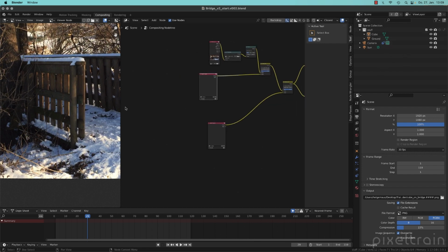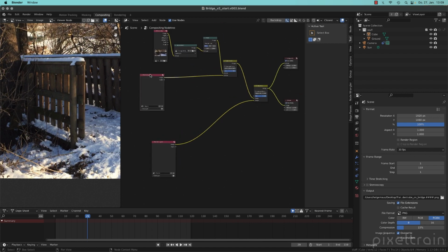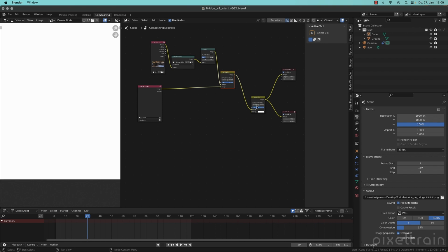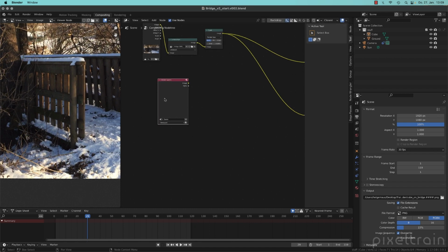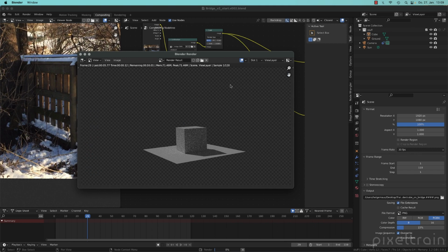And then we have to adjust this here, so I get rid of one of these render layers nodes, we get rid of these two guys. If you Control X, you will see that the connections here will stay. And this here hasn't been rendered, so if you want to render really fast, we can click here on this little render icon. So to render only that here, and now you see it renders in one step.